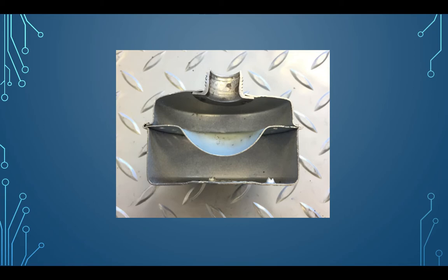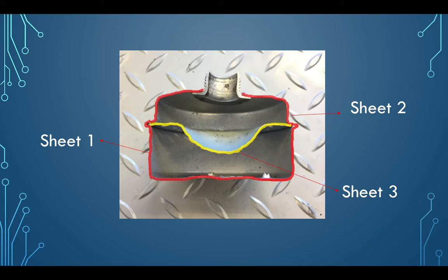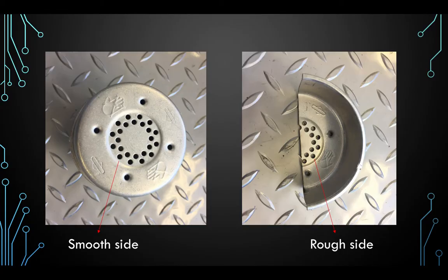As a result, two sheets were drawn into a cylindrical shape with a closed-off bottom, and when connected, created the muffler shell. The remaining sheet is mildly deformed in the center by a rounded punch to create a barrier for noise reduction. The smooth appearance of the holes on one side and the rugged appearance on the other reveal that the holes were created through unidirectional piercing. This also contributes to the safety of the part, as no sharp edges are exposed.